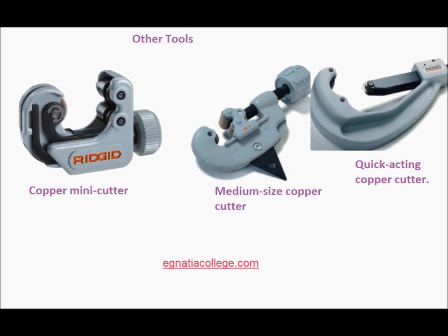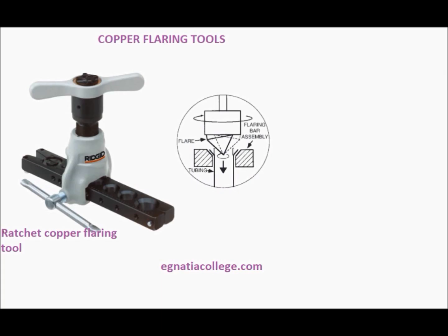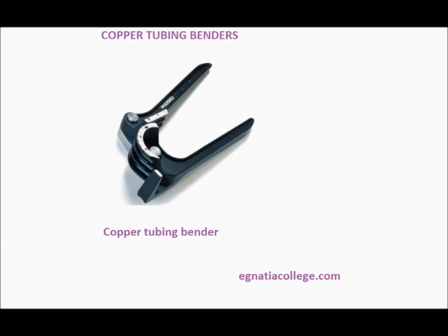Copper pipes are used more often in commercial installations than in residential due to the popularity of plastic water piping systems. Copper flaring tools. A flaring tool flares the end of soft copper tubing to create a 45 degree angle that mates with a compatible brass flared fitting. A flaring tool is clamped around the copper tubing, and the flaring post is turned clockwise into the tubing to fold the tubing outward, creating the flare.